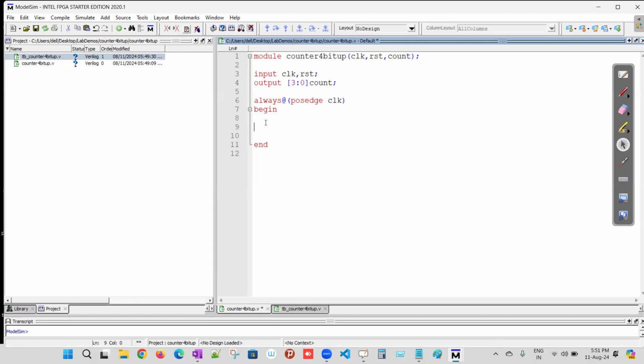So here, if reset, we are checking if reset is high. The meaning of if reset is equal to this: if reset double equal 1, you are comparing with 1. So here this double slash is for comments. If reset double equal 1, you are comparing. This is the equivalence checking operator. So instead of this, if you put just reset also, it is doing the same job. Okay. After that, if reset is high, then we are setting count to 0.